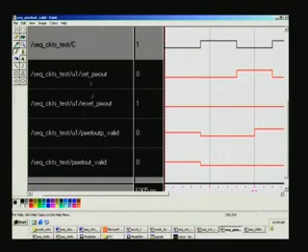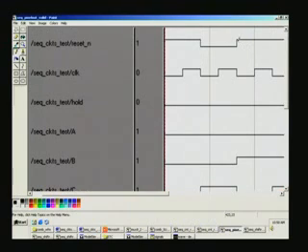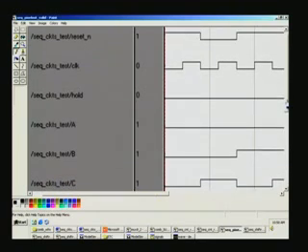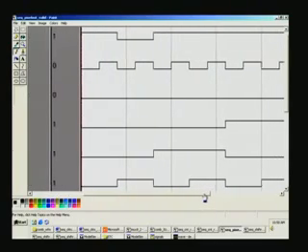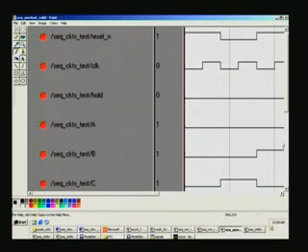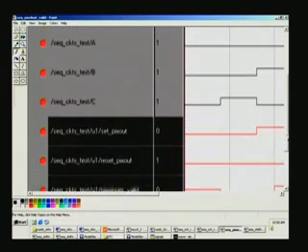And mind you, these two are assign statements basically, so they are combinatorial outputs. So they will not be reset, naturally. And coming to the normal operation, right from here and at the subsequent positive edge, it becomes active only at that point of time. So now, the only thing you have to remember is the last three here are the ABC inputs. Once again it is in binary progression, and now let us see what happens to this set and reset.